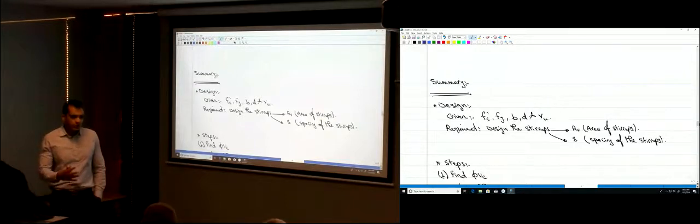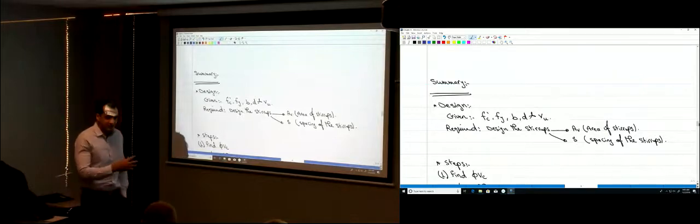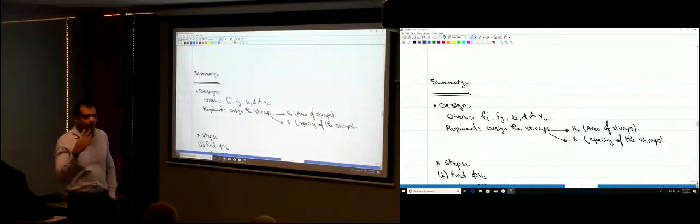How? Doing structural analysis. For the structural analysis here, this is the simplest beam. It's a simple beam. But let's say you have a large structure. Just run structural analysis, okay? Put it on the software, put the dead load, the live load, run the load combinations, and find Vu at the section that you want, okay?